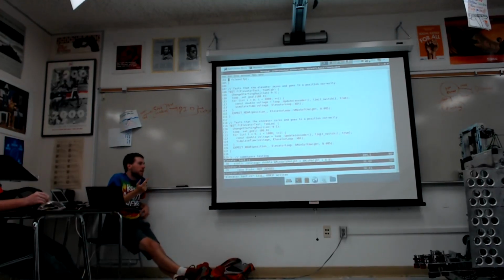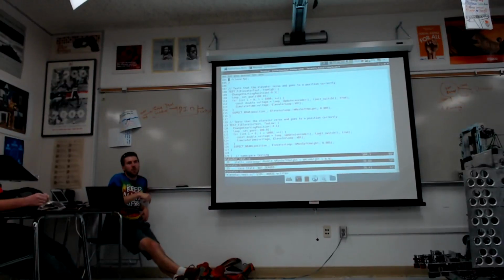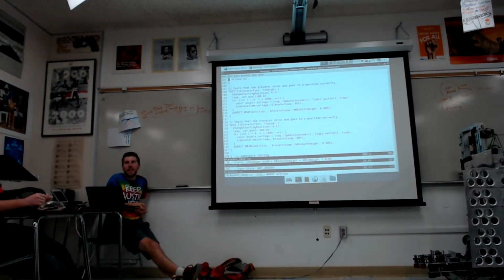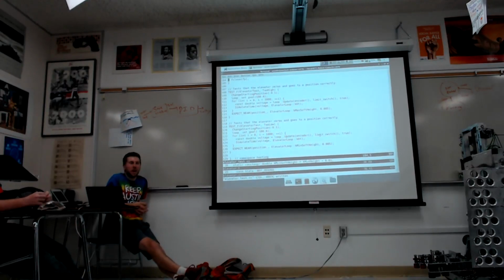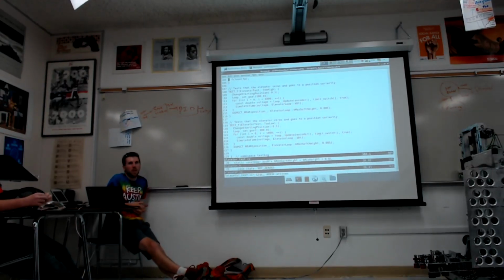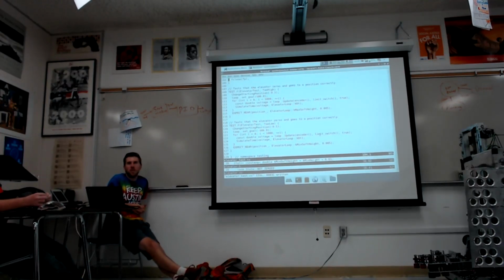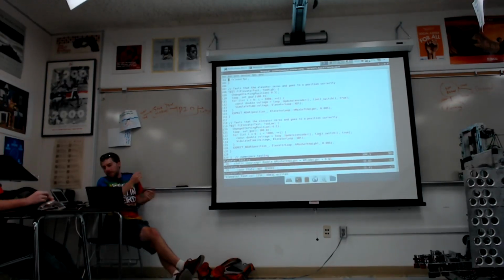And then the other thing we can do there is turn our zeroing speed down. We can make it go really slow, so it can't go very fast. It doesn't have any power. So that way we can watch it work on the hardware for the first time and make sure it looks reasonable before we then let it loose. Okay, so let's do it.